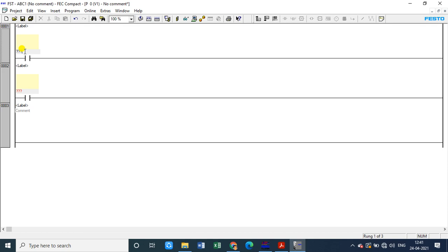But here we cannot mention those with the same name or similar style of giving name. Here what we have to do, we have to use the port numbers to which we are giving the supply from those limit switches or sensors, and the ports which we are connecting to the actuators, that is the output device.